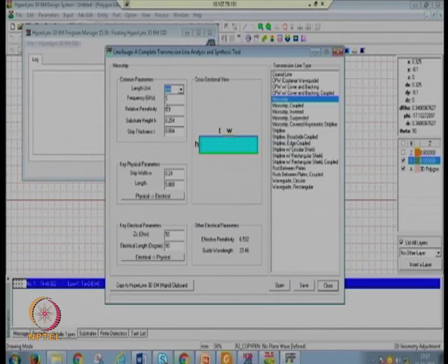You need to just give the specifications, and accordingly your effective L and W will be calculated. So, the frequency at which we are interested is 5.8 gigahertz, and this is 2.2 relative permittivity of RT-Duroid 5880, and the thickness that we were using is 0.8, and this is metal strip thickness. So, generally we take it either 0.002 or 0.004, just keep it as it is.